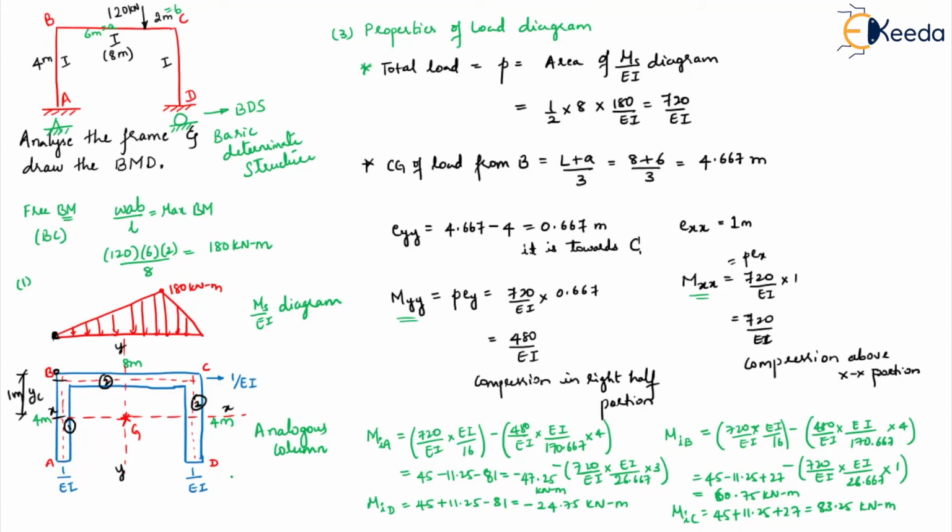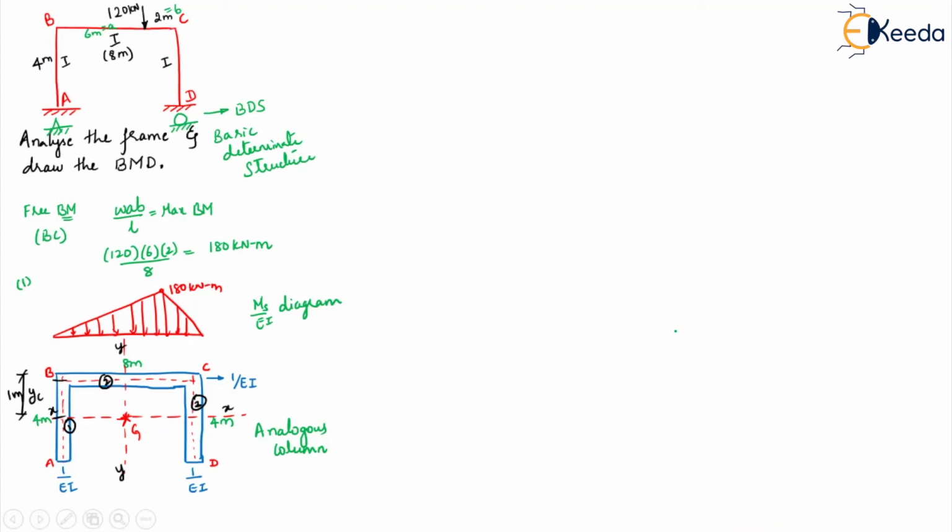Okay. Now the final step is to find the final moments. So step 4 is finding the final moments, for which the formula is MA equals MSA minus MIA. Okay, so that's 0 minus of minus 47.5, that's 47.5 kilonewton meter. This is the sway case, but this is a symmetric frame, so this will not come into this. For everywhere it will be 0.